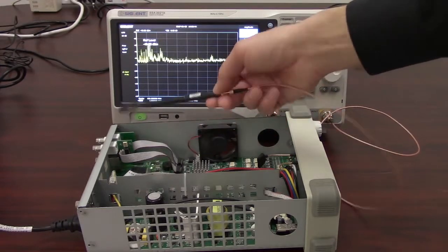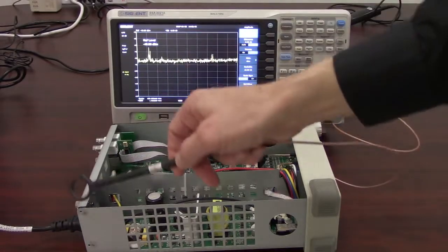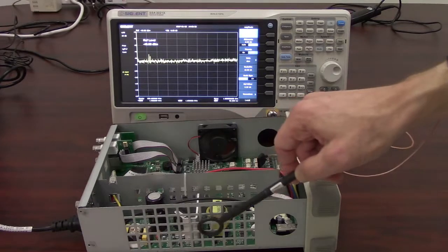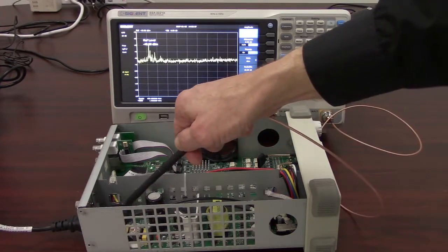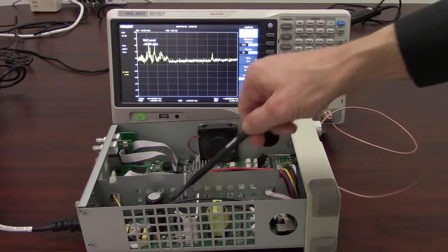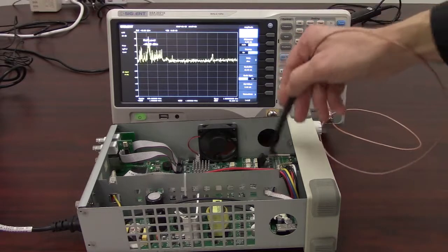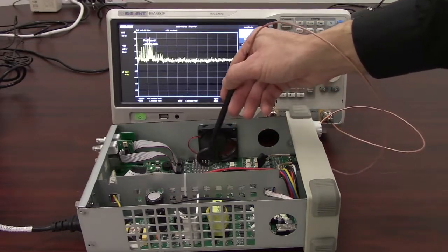And in this case, if we had the cover over this, we would be able to sniff around the cover to see if there were any leaks for EMI, and we'd be able to make suggestions on whether we needed to gasket a particular output or perform some kind of shielding in order to minimize that RFI. And basically you're just going to go across your design and take a look at the areas that are going to be the most likely to cause any issues.